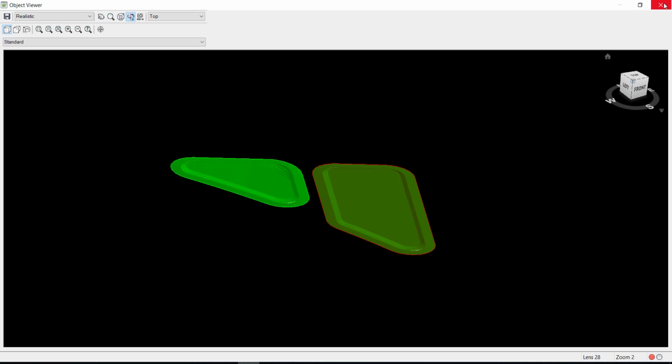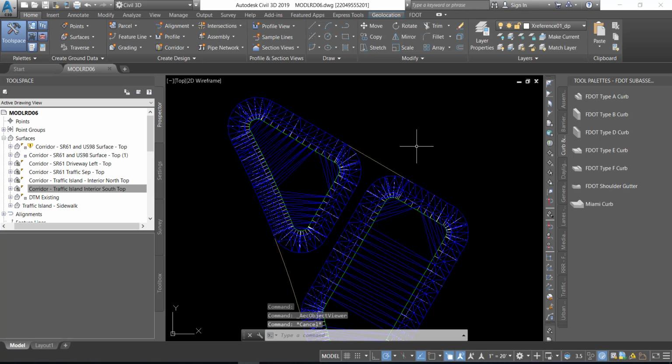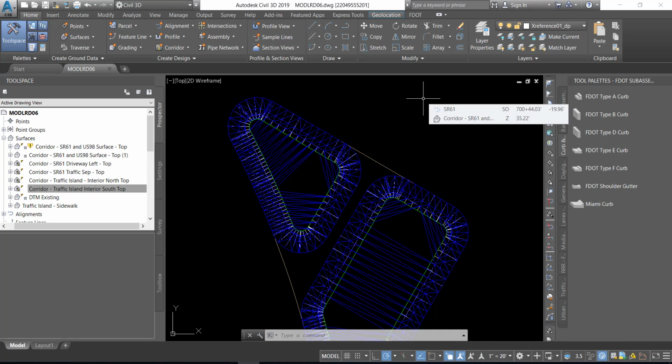After finished viewing the surfaces, click on the X in the top right-hand corner to return back to your model drawing. Press Escape to deselect your surfaces and have your ribbons return back to their default state. Exercise 9.22. Set traffic island surfaces display properties. In this exercise, you will set all the traffic island display properties to No Display.